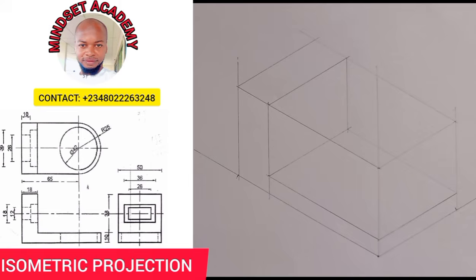Now the next thing we're going to do is start drawing. You see there are two hidden lines here, right? The plan is telling me that this is not rectangular. It is elliptical, it is circular. If you look at these two hidden lines, they represent this circle here, and this side represents this outside circle. So it's telling me that this edge is circular, and I'm going to draw a circle at this edge.